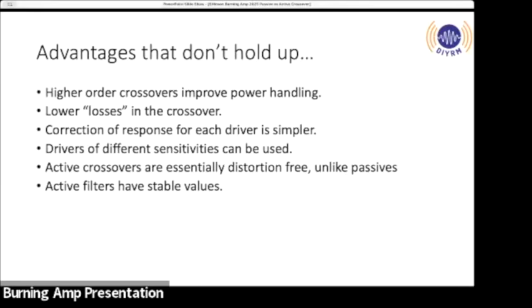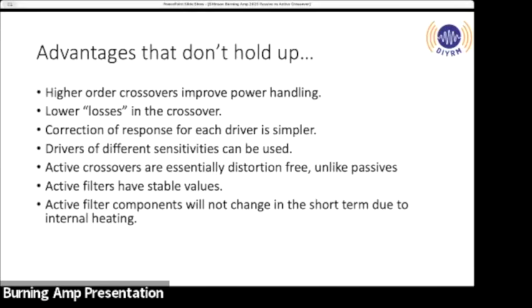Active filters have stable values. So do passive filters. That inductor and that capacitor are not changing in value much. The woofer or the tweeter might change its impedance, but I'll show you how much that adds up later. Active filter components will not change. These sort of go together, and I don't know why he wrote them separately, but I copied it. And then smaller values for caps and inductors to save costs. I'll get into that at the end.